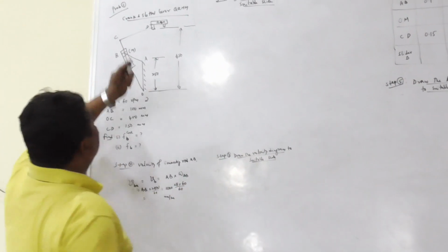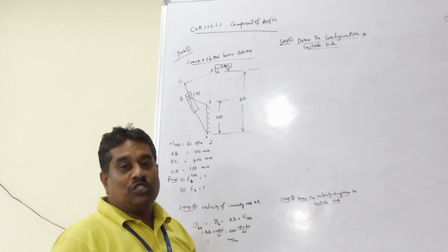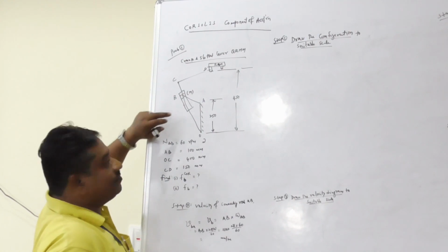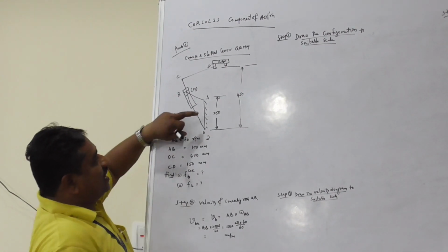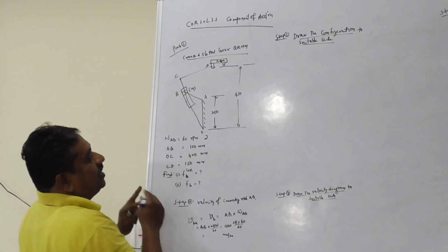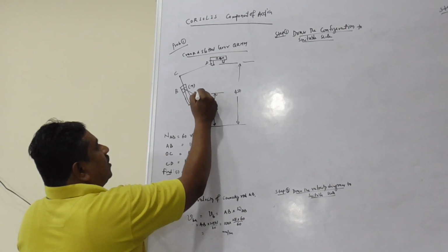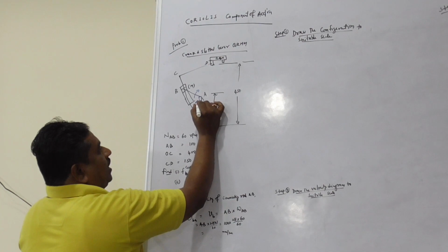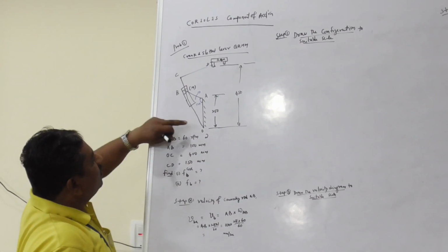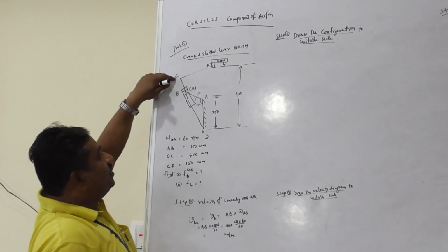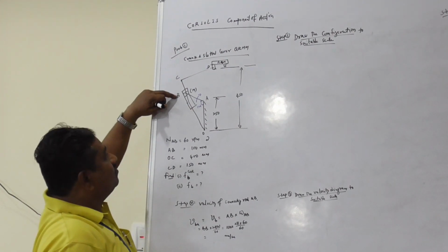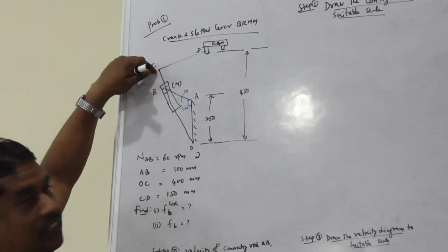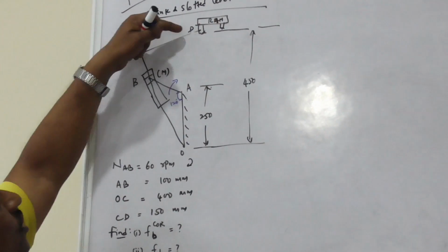Consider the crank and slotted lever quick return motion mechanism. The details of the QRMM are shown in this figure. Link OA acts as a fixed crank. AB is the connecting rod, which rotates in clockwise direction. The angle subtended by the connecting rod with respect to crank OA is 120 degrees. OC is a slotted lever which has a die block or a moving point B. M is a fixed point on the slotted lever OC. The end of the slotted lever is connected to the ram through a link CD.